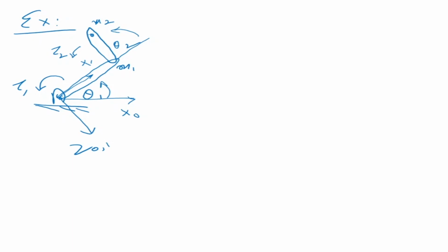Now we are using Newton-Euler. So something to note here is that we are using the Newton-Euler formulation, so we have to first do outward iteration, then we have to do inward iteration. A couple more things to note: the assumption that we are making is that the mass distribution is extremely simple, and the mass exists as a point mass at the distal end of the link.